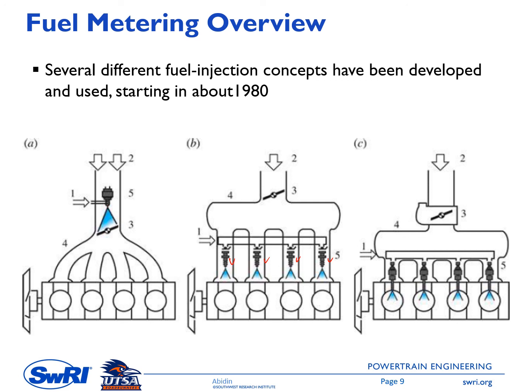Single point injection is for sure simpler and cheaper. However, there is a disadvantage in terms of transient response. For example, if you want to change the load of the engine, the control will change the air and fuel flow and so on. But because the fuel introduction is some distance from the cylinder, there will be a delay for the change of the load. B has a better transient response because the fuel introduction is closer to the cylinder compared to A.